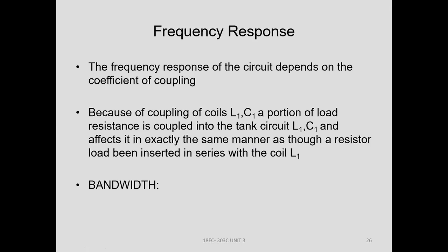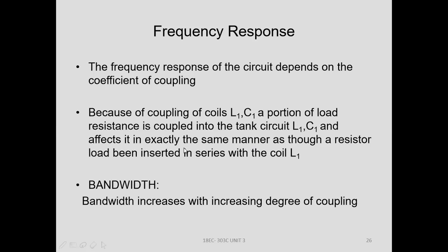So the response depends on the coefficient of coupling and the bandwidth. Bandwidth is increasing with increasing degree of coupling. This double tuned circuit bandwidth is more compared to the single tuned circuit. How much the bandwidth increases depends on the degree of coupling.